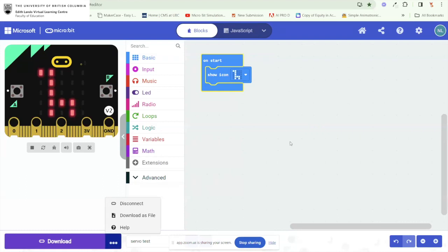And then it will say, okay, now you need to actually connect it. Click it again, and a white window will appear here. It will have your microbit on the very top up here. You want to click the microbit. It'll go blue, like a blue line across it, and then click connect. So once you do that and you click back on these 3 dots, rather than say connect anymore, this will now say disconnect, which means that your microbit is connected. I know it sounds kind of backwards and weird, but that's how it is.